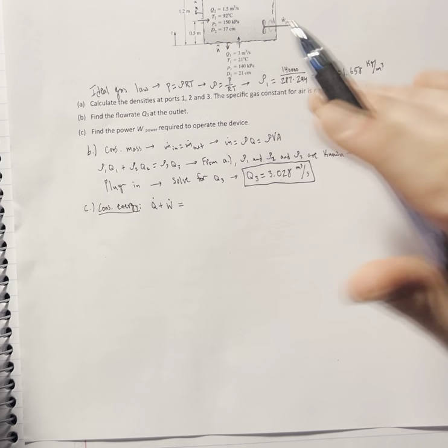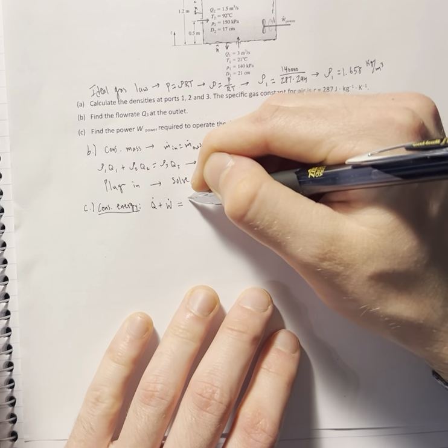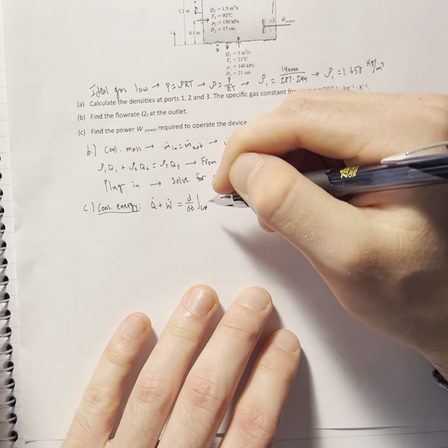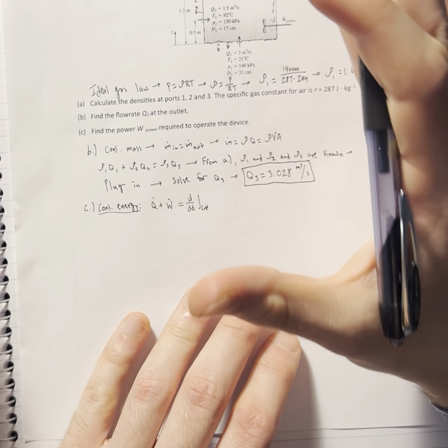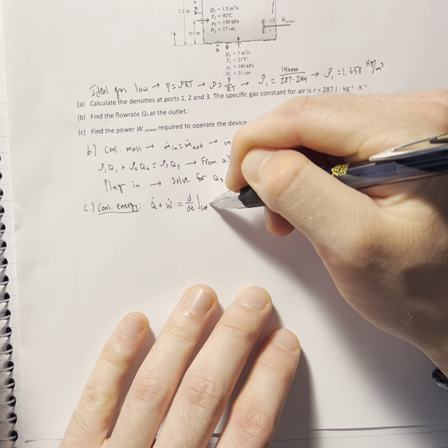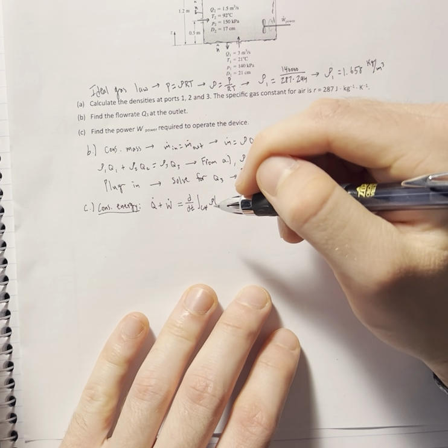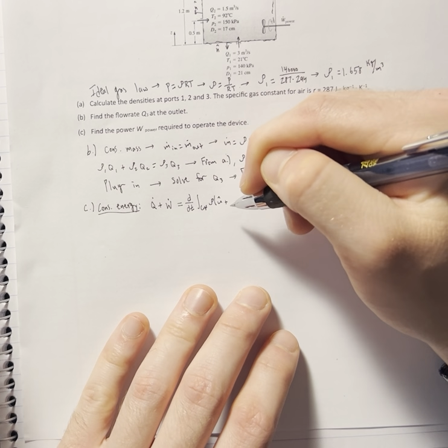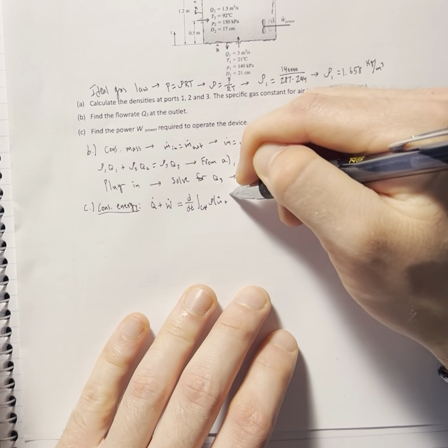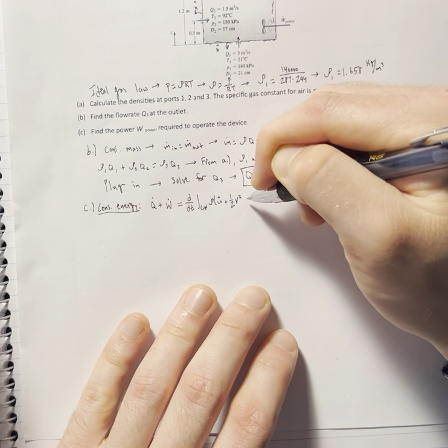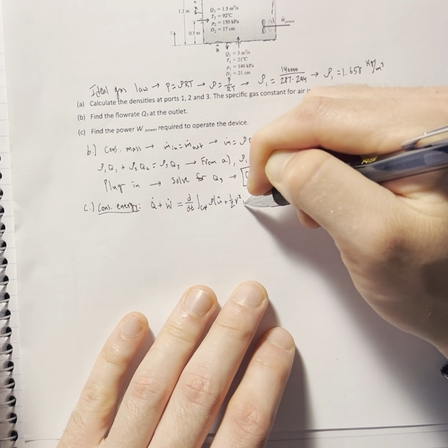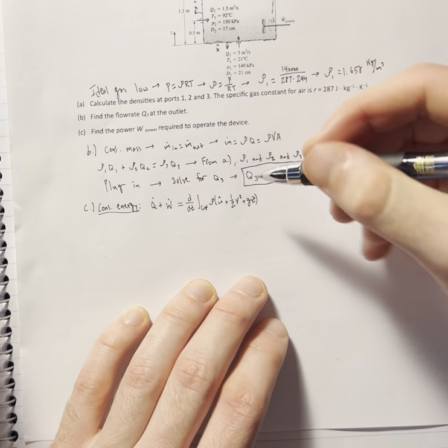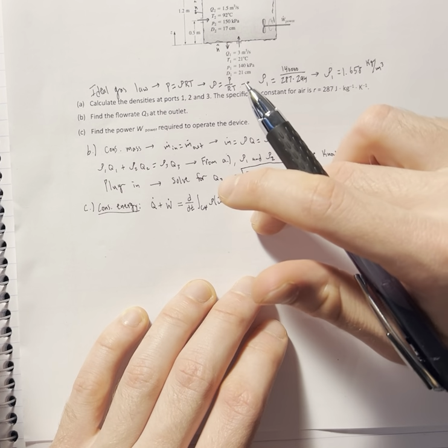It's equal to, as usual in any sort of transport equation, the time derivative term, which will go away. And this is really the only equation I don't have super memorized, because I just don't have to use it all that much. It's density times, in parentheses, U hat, which is the specific internal energy, plus 1/2 V squared, which is the specific kinetic energy, plus gZ, which is the specific potential energy, times the dV term.